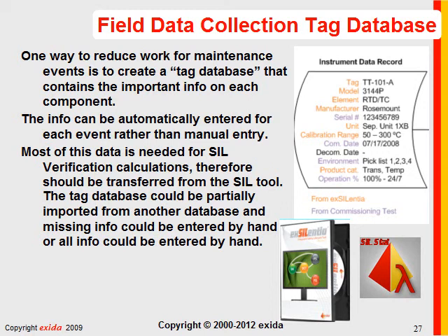A barcode scanner hits the instrument and knows a lot of information immediately, like the instrument tag, the model number, the manufacturer, the sensing element if it's not part of the purchased model. You can buy a temperature transmitter, for example, and not know whether it's being used with an RTD or a thermocouple. The serial number should correspond to the instrument tag. What unit is it installed in? How is it calibrated, which gives you some information, even about the environmental limits, perhaps.